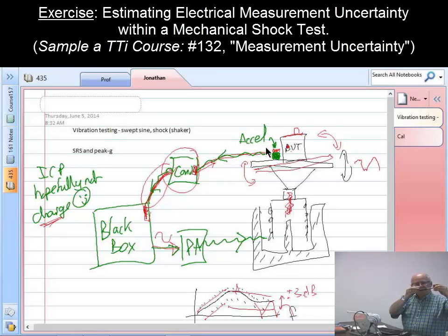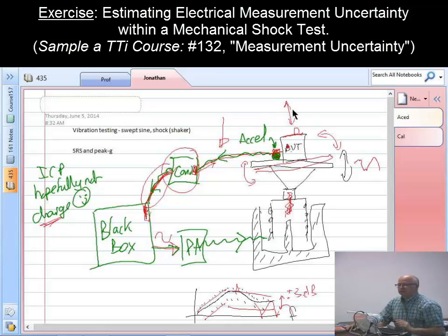Depending on whether the accelerometer is on that side or this side, because we can't get in the middle, then with that angle and that distance, we're going to be under-reporting by 1%, 2%, whatever it happens to be. So that's an experiment we could set up to try and check the quality of the translation. Coupled with the accelerometer calibration here, those two will give us an indication of how good the signal at this stage is compared to the required translation of the platform.